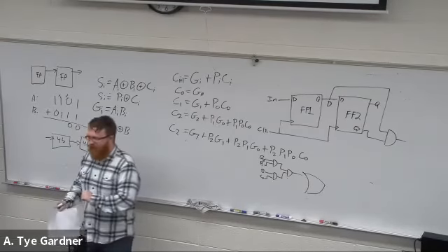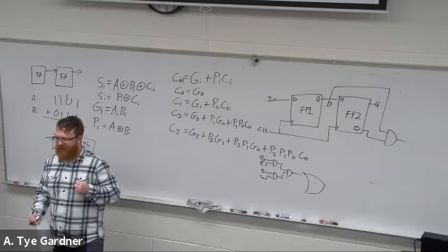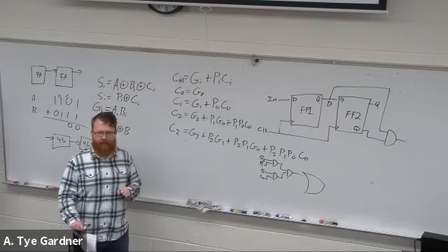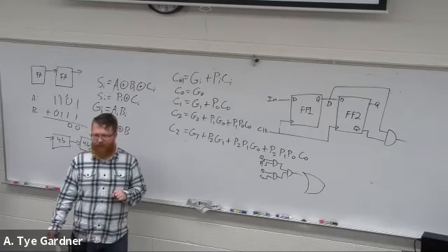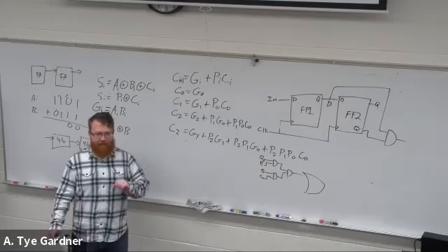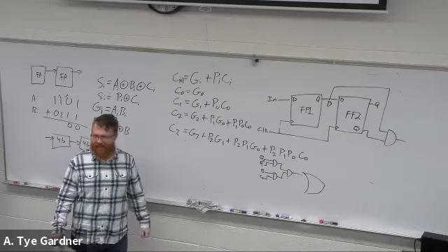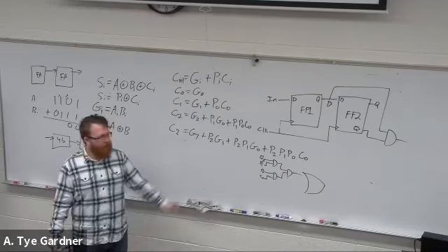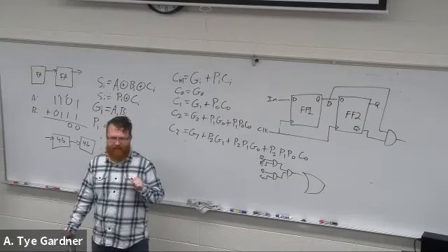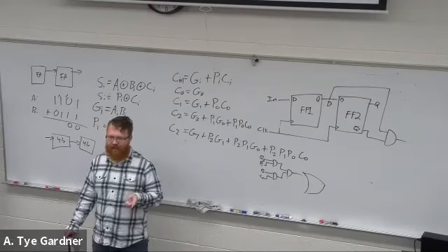And what's nice is on your FPGA, this does not implement in 2 input AND gates. It actually probably implements in a lookup table, like I've been having you guys puzzle through the last couple of homeworks, right? Because those are fast. It's just a mux, right? It just throws it in and outputs it. It has like 3 gate delays and you move on. So this can get very, very fast when you're doing it that way, but it gets very, very complicated. The size of your logic gets very large to do this.